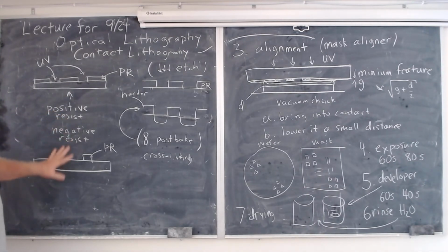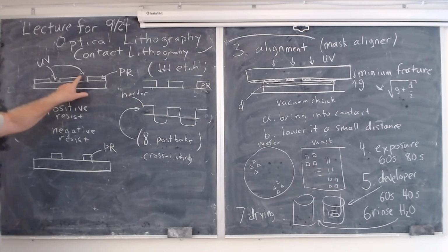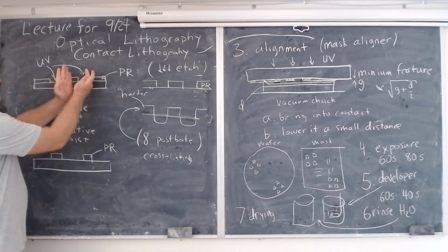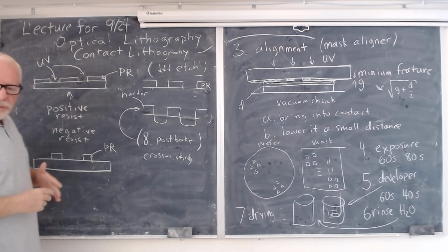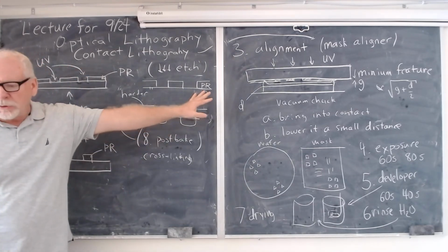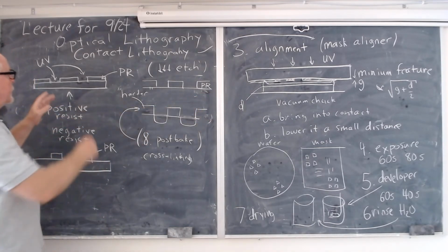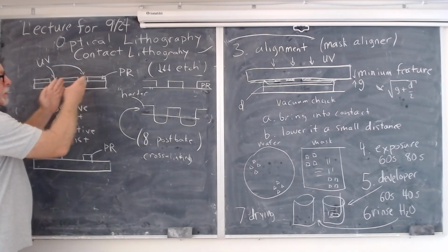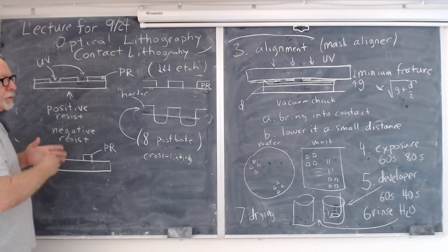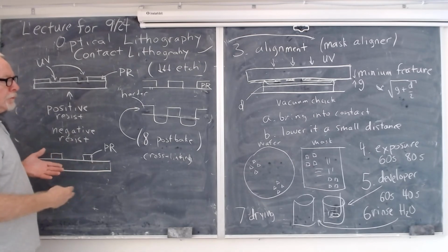If you think about it, because this part is getting removed, for positive resist that hole may become slightly bigger than your feature on the mask, because you expose it out and develop a larger hole.